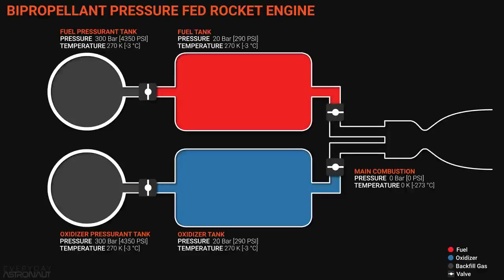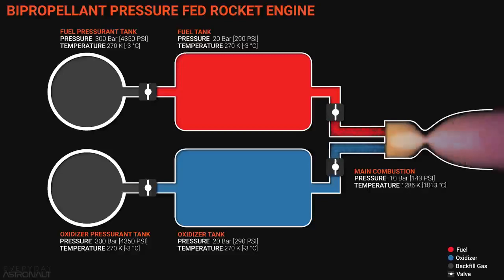They still are very simple and rely only on a few valves opening to actually operate. A pair of valves will open the fuel and the oxidizer tanks to the engine, and then another set of valves maintain adequate pressure from the pressurant tanks to each of the propellant tanks. The advantage of a biprop system is you can utilize a more energetic and efficient propellant.